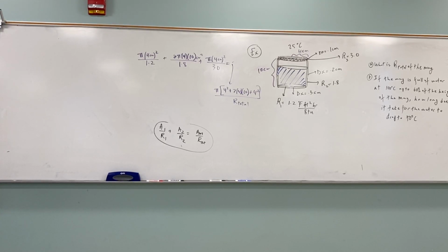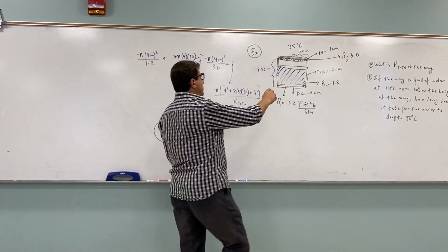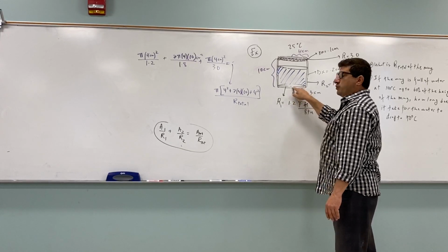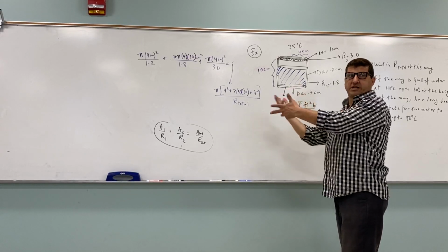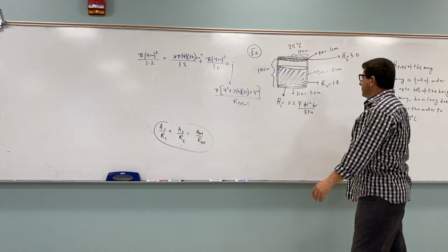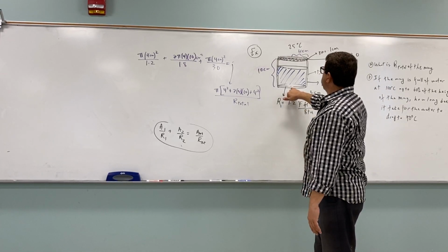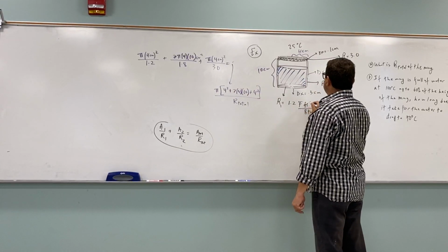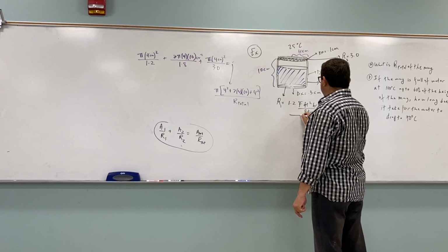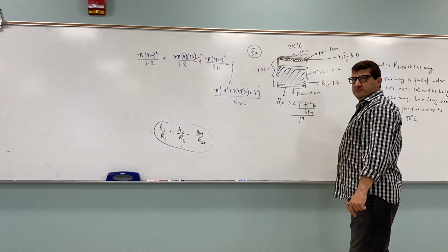So in other words, the bigger the thickness, the bigger the R value, right? So they're normalized to some thickness. The inch ones were normalized to 1 inch. So what this means is the R value of this is 1.2 if it's 1 inch thick. You see? If it's not 1 inch thick, then you've got to multiply it by the thickness, whatever the thickness is. So basically it should be written like this: Fahrenheit, feet squared, hour, BTU per 1 inch of the material, right?